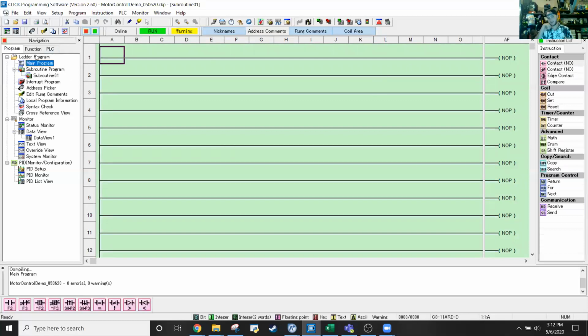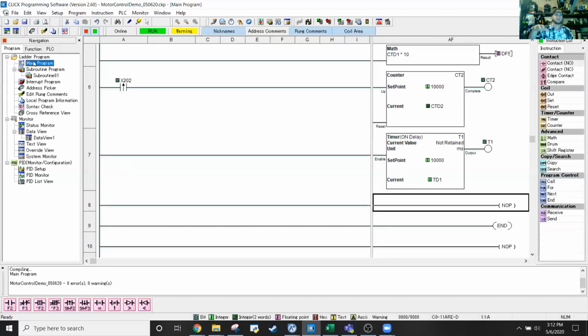So your main program might be super simple, where you literally just have 5 different rungs that call 5 different subroutines, and then your subroutines are your operational modes. If you were doing sequencing diagrams for that, you would show whatever stimulus kicks you into those different operational modes, and that might be a virtual input from a touchscreen, and you would call it out as such. Sorry, I know I'm really bad at giving short and concise answers.